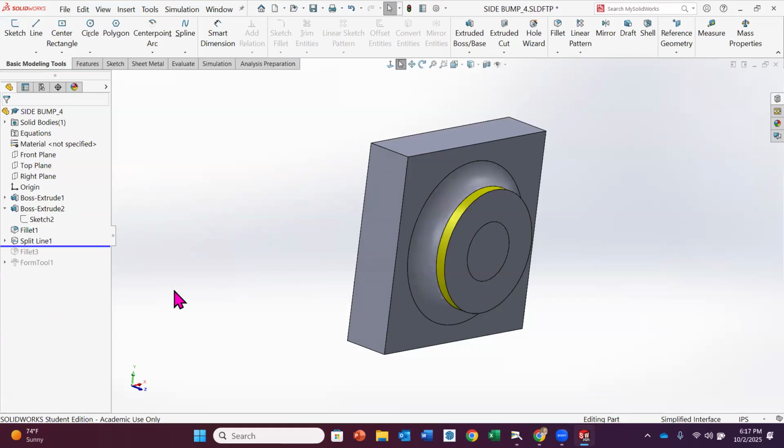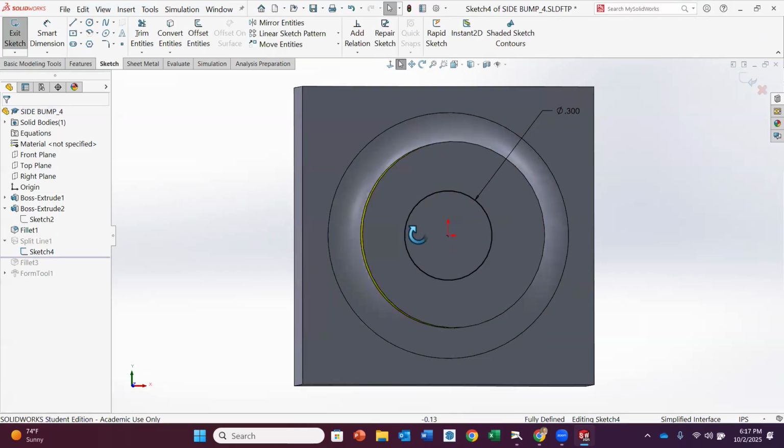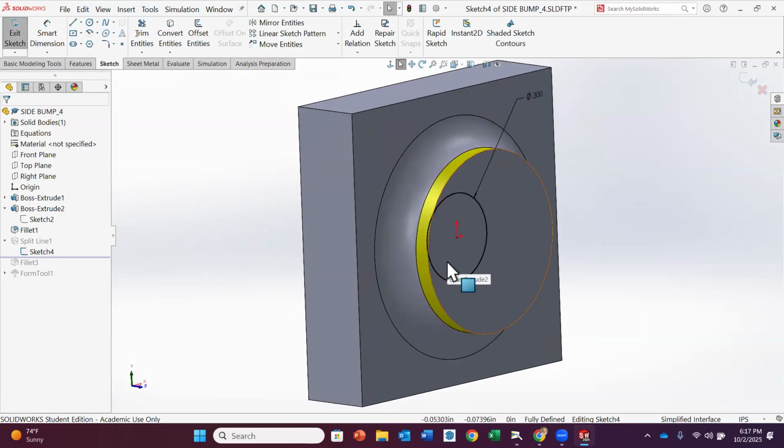And then you'll notice this split line business. The split line business was in the tutorial. When you do your split line, this is another thing to keep in mind, because they didn't make this clear in the tutorial. If I look at my sketch, it is on that front plane. Even though there's a surface out here and our gut is always going to be to go on that top surface to make the hole, no. You've got to put that sketch on that front surface, that stop plane, and then project it up with that split line command.